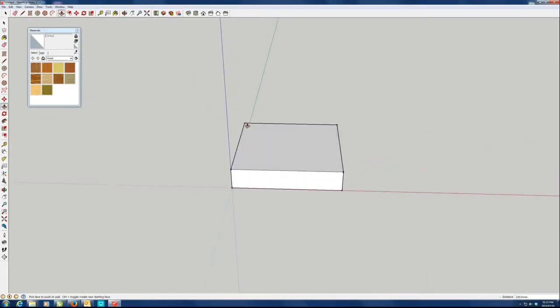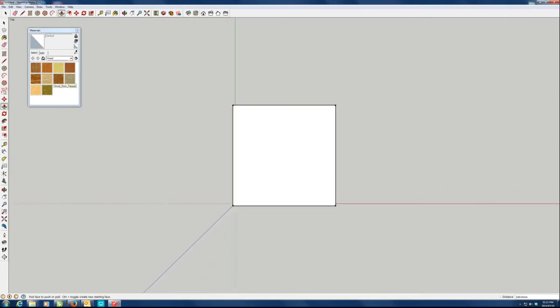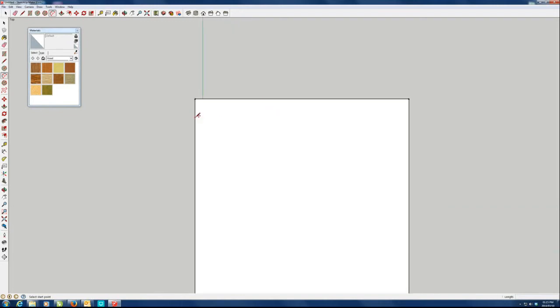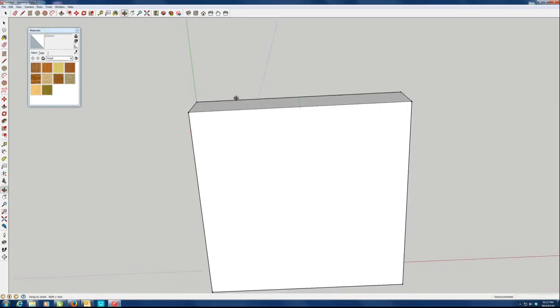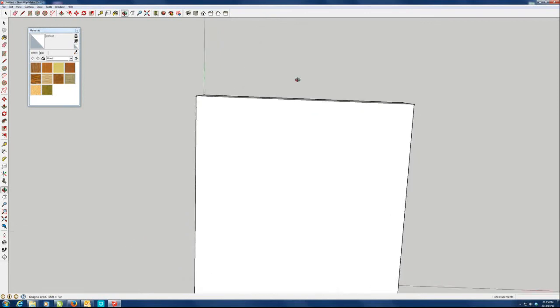Now, what I want to do is I want to round off the back of the chair. So I'm going to view it from the top, and I'm going to draw a 3-point arc. Click on this edge, click on that edge. Let me go again there. So top view, move a bit closer. Alright, one edge onto the other edge, and for some reason, oh, there we go, that is fine.